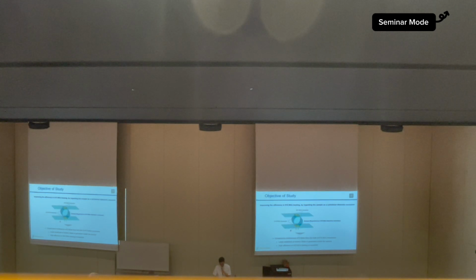If this sample is regarded as a resonator, the constructive interference of E fields from both sides of the 915 MHz resonators occurs, and then a large amplitude of electric field is generated inside the sample, and high efficiency in 915 MHz heating is expected.